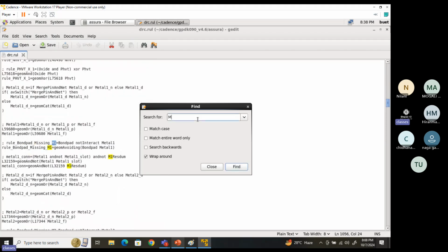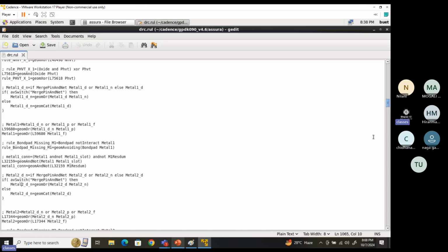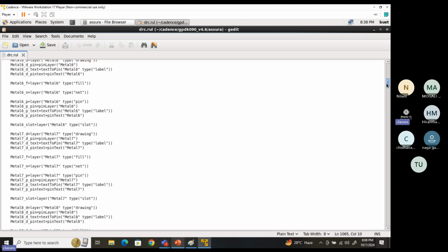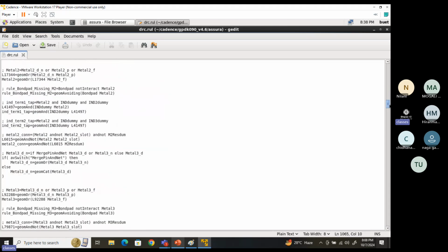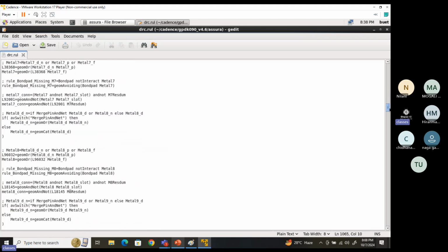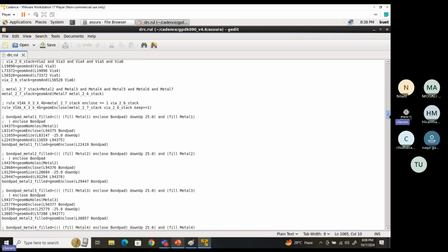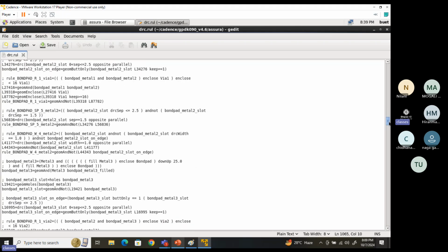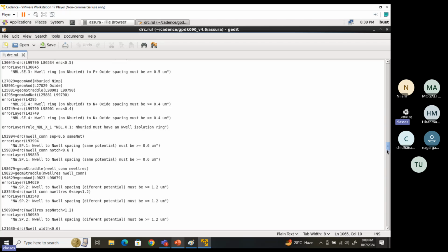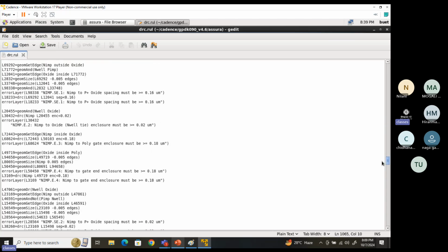Okay. ETL metal. This should go fine actually. Metal 1 to metal 1. Okay, so these are the actual rules which you generally use in your design to read the tool, and it tells you that these are the values which you should be maintaining as per the DRC deck actually. This is called a DRC deck. Okay, so it has been written by some guys in the industry. It's in skill language actually.